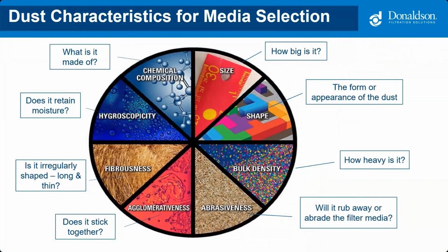And so you really gotta make sure that you're applying the right dust or the right filter to the right dust. How big is your dust? Is it really abrasive? How much does it weigh? Does it pick up moisture along the way? And so you really have to know what you're picking up before you throw in a filter bag.